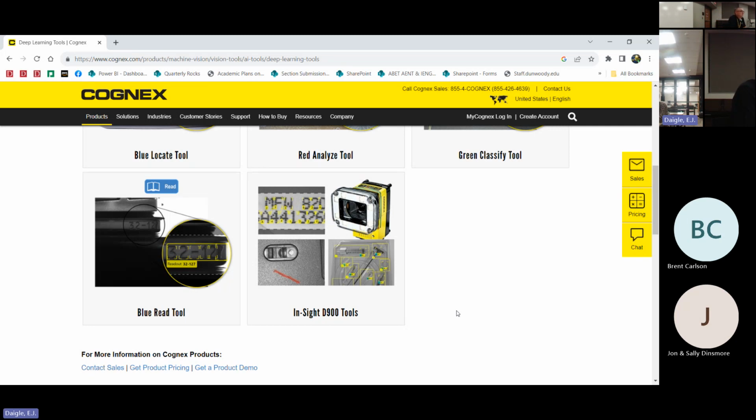Some of these Keyence systems, they actually make Keyence systems that have a big, huge computer, and you can throw a ton of parts on like a bed. It'll measure all the parts and give you a report back on all the parts. So you're not just measuring one part. You could dump a bunch of washers on a table, and it would measure all of them. Wow. Yeah, so that's more of a laboratory grade inspection system. If I am doing, say, on the industrial automation side, Cognex is where it's at. It's really, really good for filling bottles, making batteries, doing something where I'm looking at every single part coming in online and making sure we don't make a bad part.